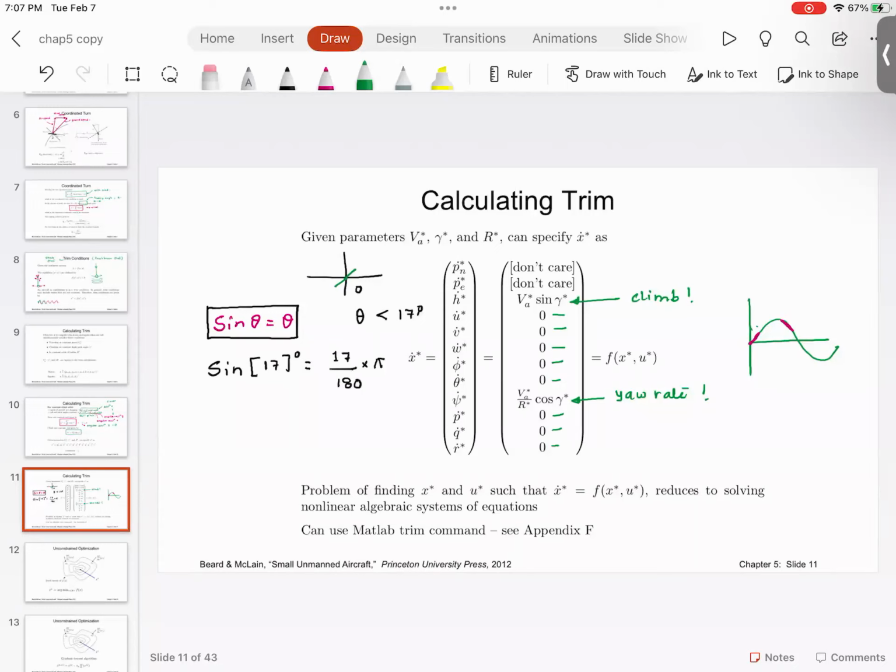If you use an exotic nonlinear control, you can get a very good journal paper out of it. Maybe you can show its implementation on a few cases, but you cannot prove that it will work all the time unless you use some type of Lyapunov or global control theory, because nonlinear controls are typically local controls. So even if you want to use it, FAA will not allow it, because you have to prove that anything that goes on the aircraft, whether it's hardware, software, a piece of code, or a piece of bracket, has triple redundancy.